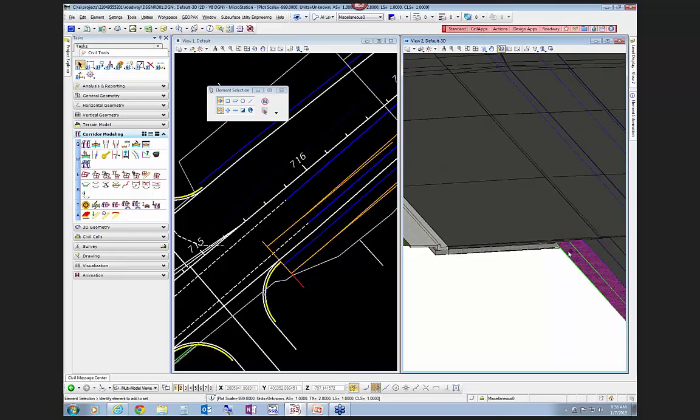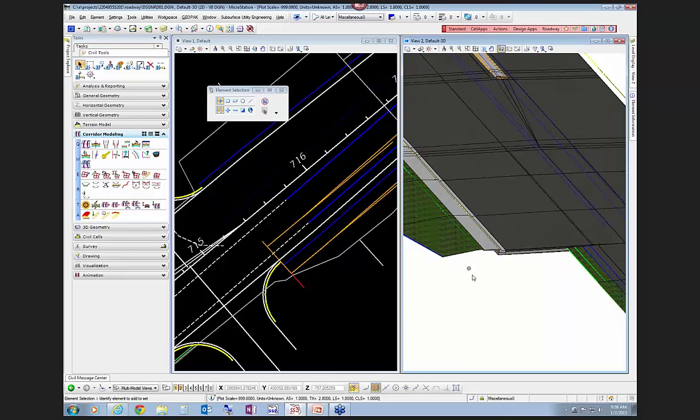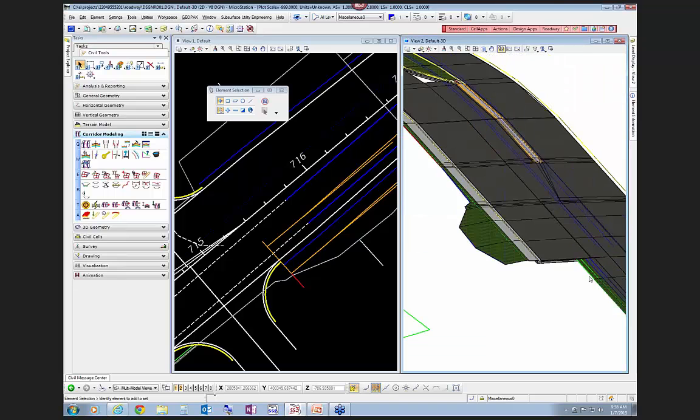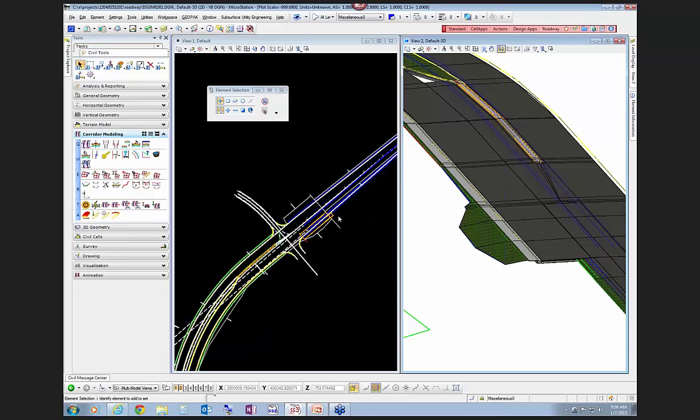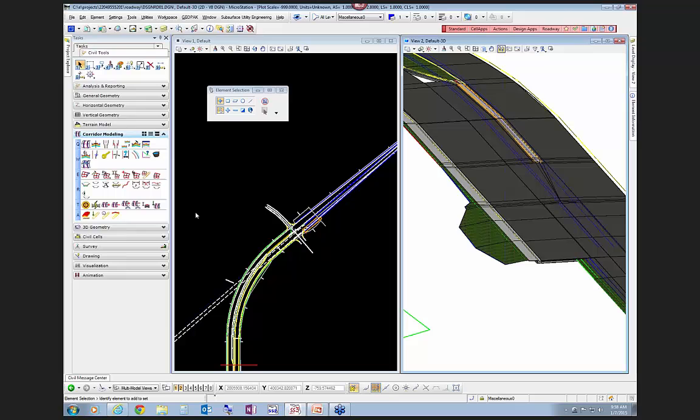But once you have put another linear template in here, you could essentially run your template without an end condition on the outside, and then use these linear templates to place whatever you want, and you would just have to put them along your corridor as they apply. So, you know, there's three or four different ways of doing it.